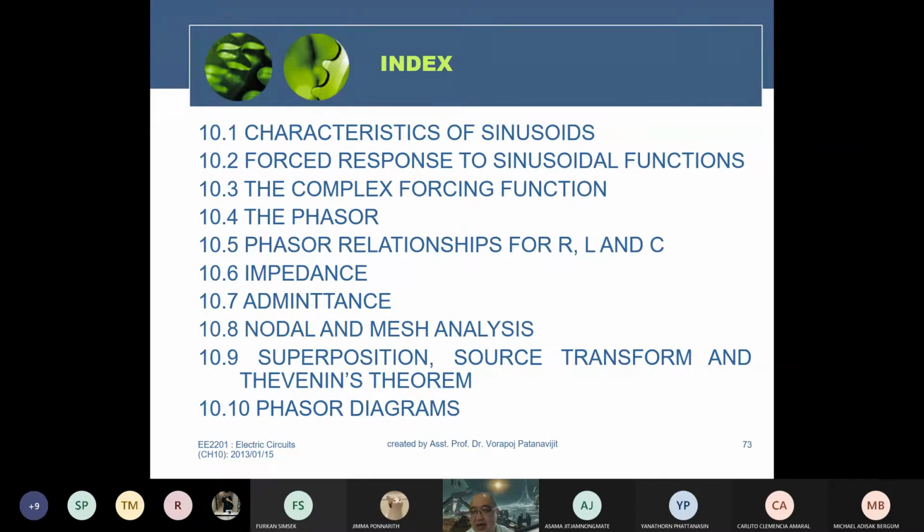You convert the resistance, inductance, and capacitance into impedance form, and you can apply Ohm's law, Kirchhoff's voltage law, and Kirchhoff's current law. You can use the current divider or voltage divider techniques. Everything that you compute in the Phasor domain is the same as DC circuit analysis, but a little bit different: every number, instead of being a real number, is a complex number.